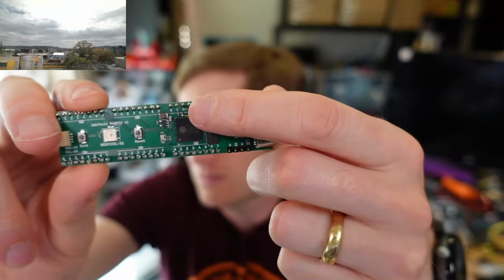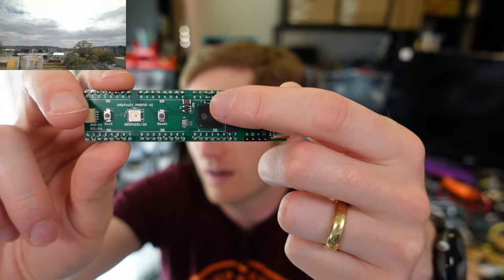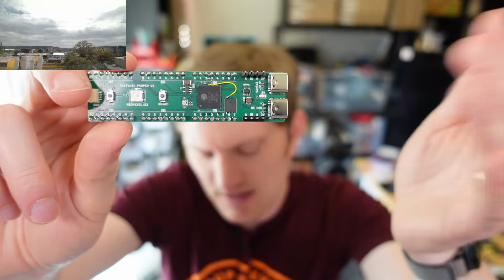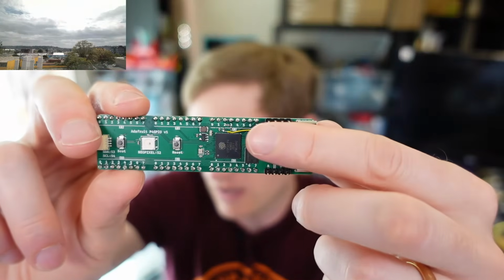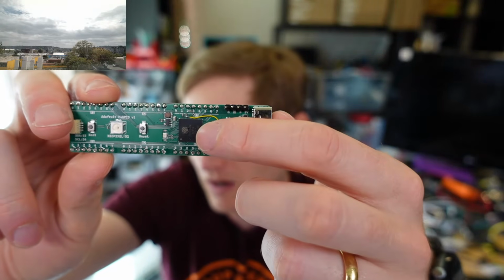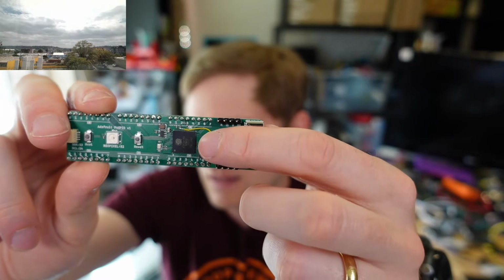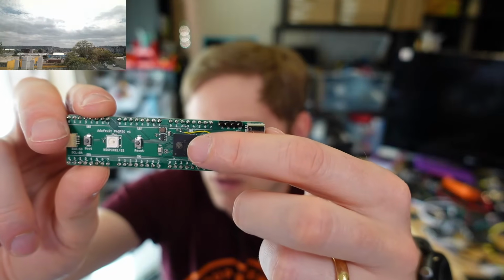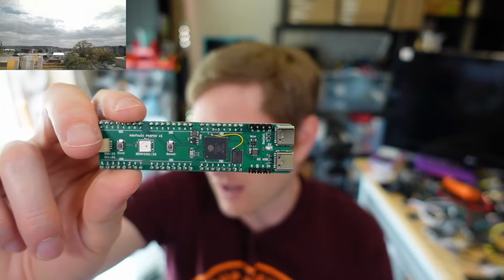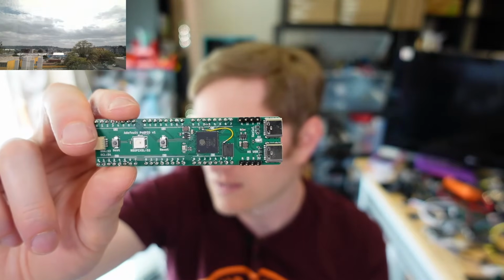The ESP32-P4 has its own regulator to give you the voltage that you need for the flash, which is actually the same voltage that I'm putting into the P4, but it has the ability to do 1.8 if you want. And that's coming out over here. I thought there was a thing in the chip where it would take it to another power pin over here and output from that other pin. But the reality is that that's a power input for the I/O voltage to go to the flash. So I failed to connect those two things. That's why I have the yellow jumper wire, and now it works.